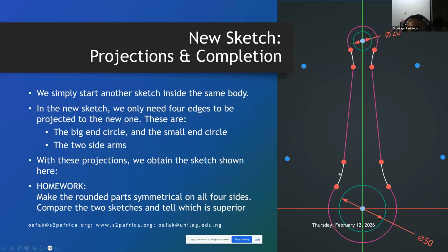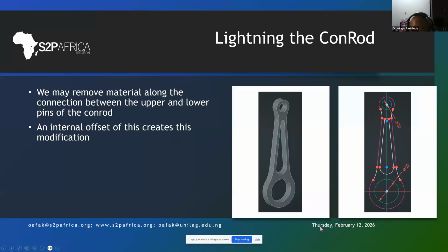If you offset it inwardly, after you have done it, you are going to get something like this. After you got this, you can then remove the newly added arcs, and that's it. That's how you get this. Once you do that, you'll see that you now have something that can be extruded. I just extruded it for 10 units, and I got this. Usually, in this particular case, you are likely to need to do it for 15 units.